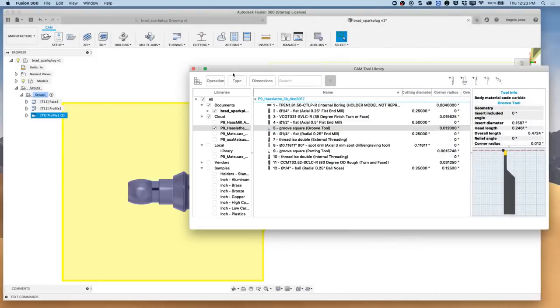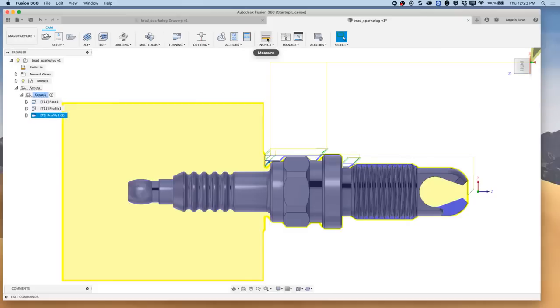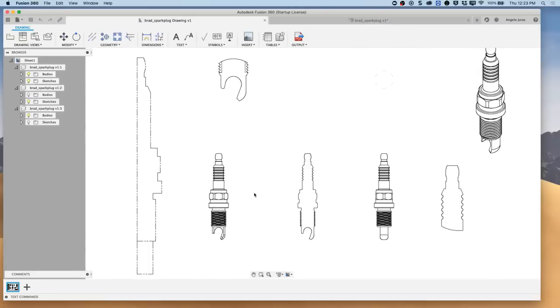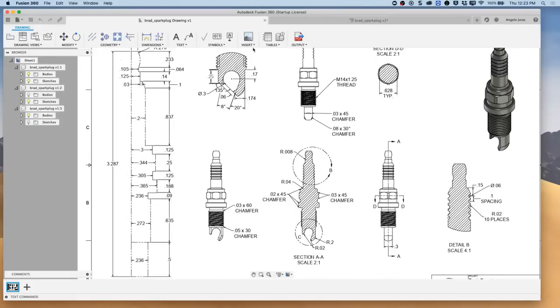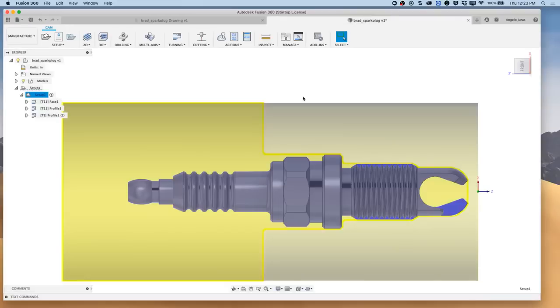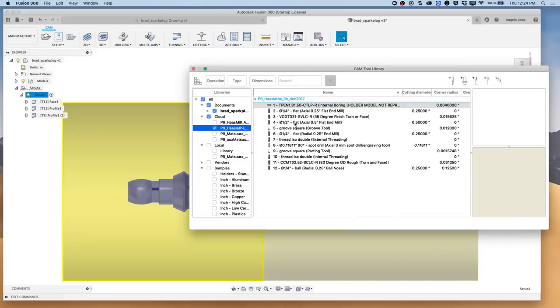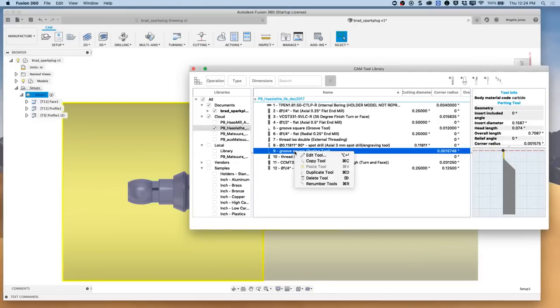Let me see something here. Let me close out there. Let me inspect. Actually, I can just go into here. Do we have that groove width dimension? Yeah. Okay, so this groove here is 90, 125, 125. Okay, so let's come back here and go back to our tool library. Let's see what tool I have can fit in there. So I know I have this tool, but that's a parting tool. It doesn't really groove very well if I want to clean that up to surface finish. Okay, I'll come back to that.